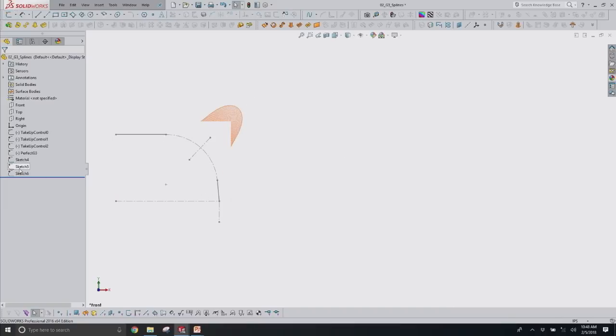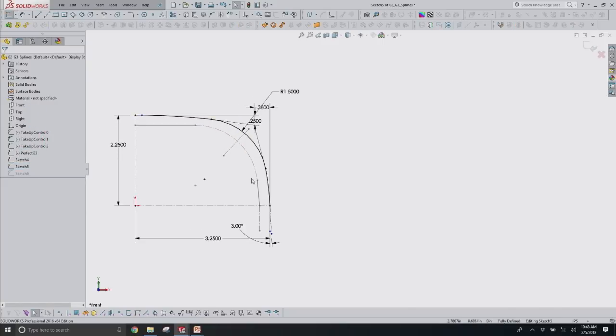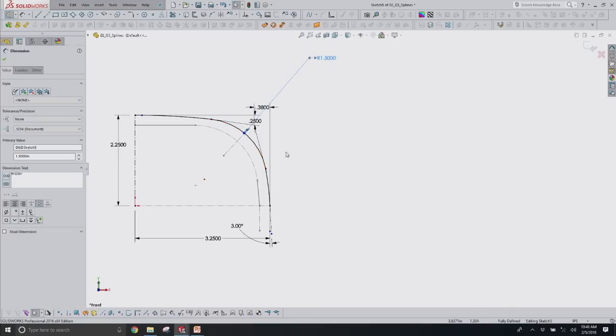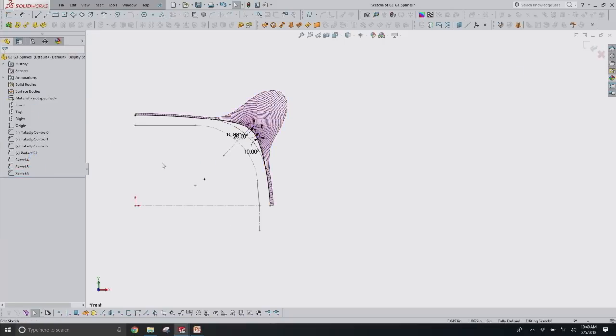It's a little bit harder when we use an arc. So here I have two arced line segments. I've defined the size of the radius I want with just the standard fillet tool. I find this is a great way of easily dimensioning the size of spline-based blends. Just define the size with the standard fillet tool. And then I just have a habit of converting into the next sketch.